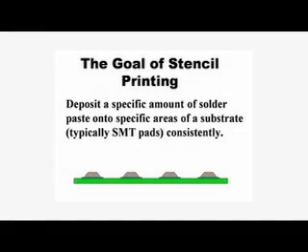The goal of stencil printing is to deposit a specific amount of solder paste onto specific areas of a substrate. These areas are typically surface mount pads. This needs to be done consistently in a mass production environment.